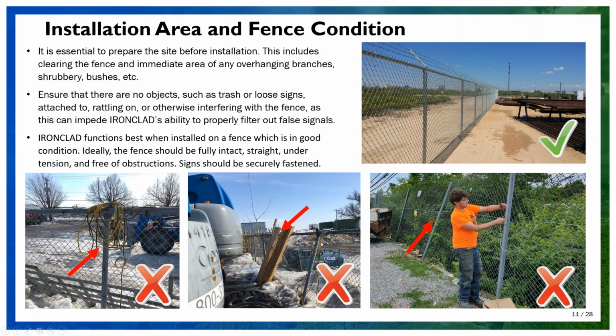As a whole, just to give you an understanding, the system can work on every fence, whether old, rusty, nice, or clean. But the things you need to avoid when you're selling a fence system are debris or junk lying on or against the fence, and we cannot have a fence that is barely standing and expect it to work. We prefer that the fence be as nice and as taut as possible to be able to detect with the highest quality and separate false alarms, like the low frequency vibrations from wind, from the high frequency impact of cutting and climbing.